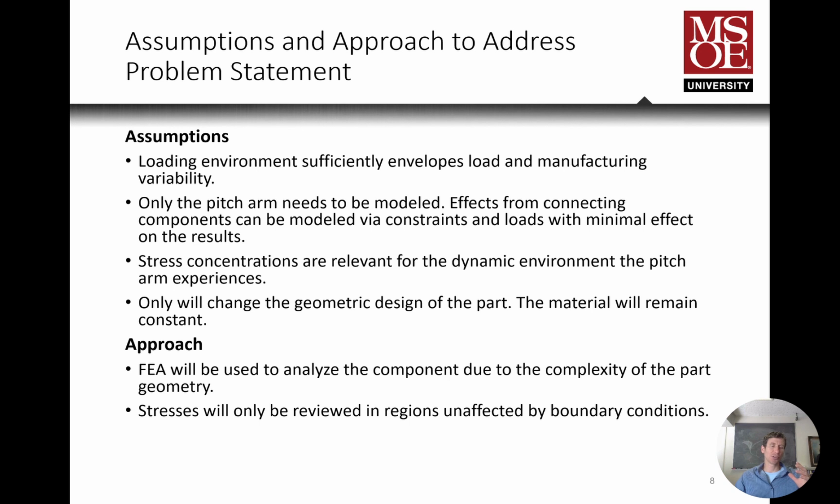And we're also going to make sure that we look at the stresses not affected by boundary conditions. And this is important because boundary conditions are an assumption, right? We're not actually modeling the helicopter, we're not actually modeling the connection, and if we were, we probably wouldn't be modeling it very accurately. So the stresses in those regions are very suspect.